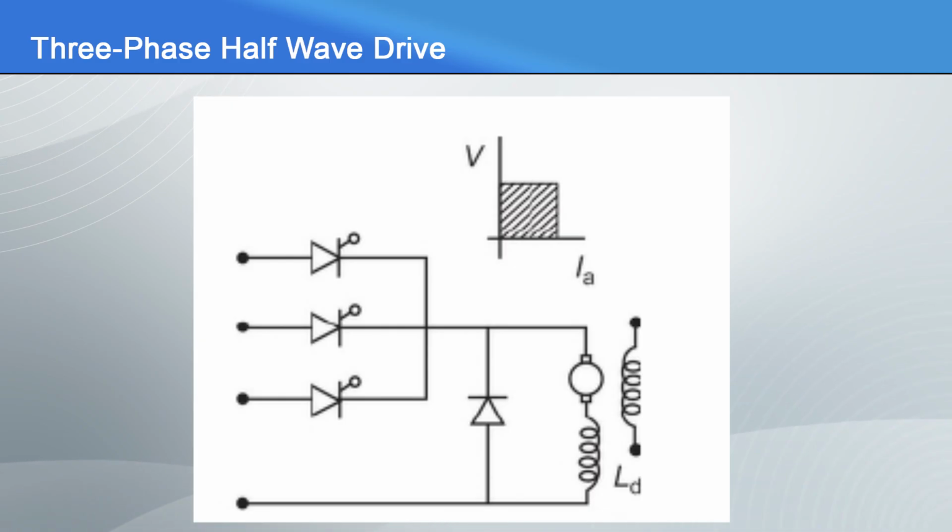The drive is preferred if not regenerating. The free wheeling diode improves the line power factor, besides providing the beneficial effect of decreasing the ratio of peak to average and RMS to average current of the load by providing a kind of smoothing of the load voltage.